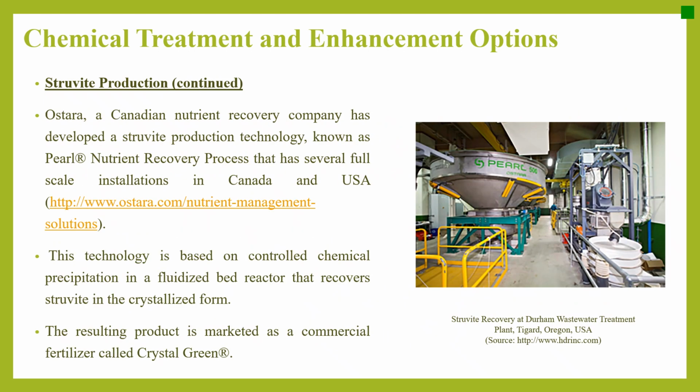Ostara, a Canadian nutrient recovery company, has developed a struvite production technology known as the Pearl Nutrient Recovery Process that has several full-scale installations in Canada and USA. This technology is based on controlled chemical precipitation in a fluidized bed reactor that recovers struvite in the crystallized form. The resulting product is marketed as a commercial fertilizer called Crystal Green.